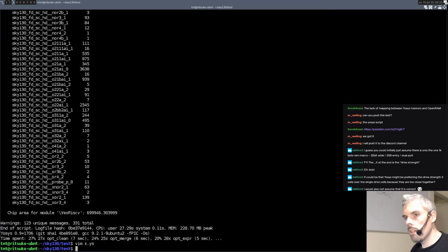Is Yosys the one that's gonna decide the drive strength to select based on the fan out, or will the place and route decide the drive strength? Maybe that particular output cell is driving a lot of nets, like 16 of them, but they're all very close to each other, which means we're not going to have a lot of capacitance.